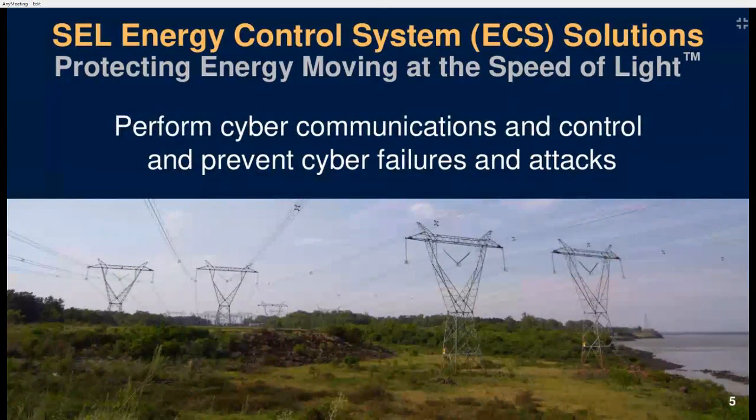Our focus on engineering investment in R&D and our culture of creativity leads to breakthrough technologies to focus on the physics of power. Energy moves at the speed of light, and protection systems have to be fast in order to make these decisions quicker. Applying new principles to protection has resulted in tripping times that are 10 times faster than phasor-based protections that we used to have. To put this in context, as a general rule, for every 1 millisecond that you can reliably trip faster, you can put about 10,000 more households of power over that same infrastructure.